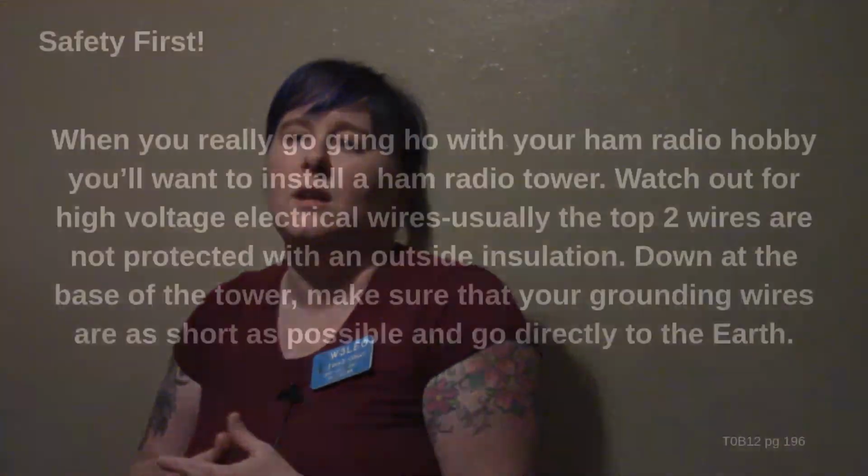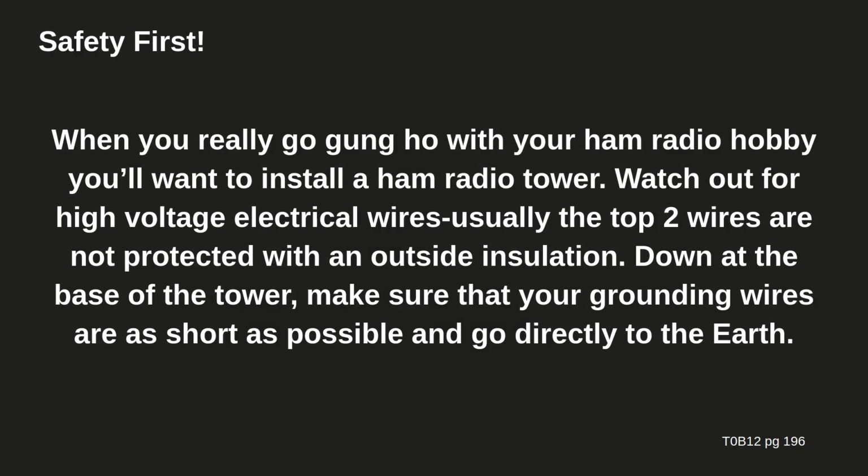Okay. When you're really gung-ho with your ham radio hobby, you'll want to install a ham radio tower. So again, watch out for the high voltage electrical wires. Usually the top 2 wires are not protected with outside insulation. Down at the base of the tower, make sure that your grounding wires are as short as possible and they go directly into the earth.